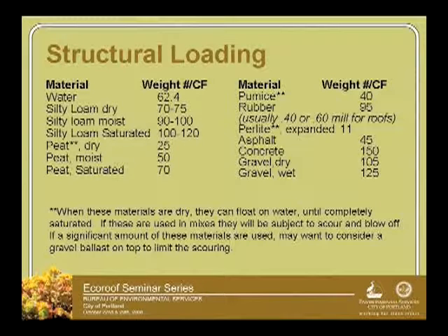But I did want to point out that with pumice up at the top there, so 40 pounds per cubic foot, if we wanted to get that in maybe a number that we understand a little bit better, let's just divide that by 12. So that number is 3.33 pounds per square foot at a 1-inch depth. Does that help a little bit? So then if we did 4 inches of that, we're at about 10 pounds. So 10 pounds per square foot at a 4-inch depth for that number at pumice. Now, pumice, of course, can vary depending on the coarseness and those kinds of things. But that just gives you a little bit of idea.